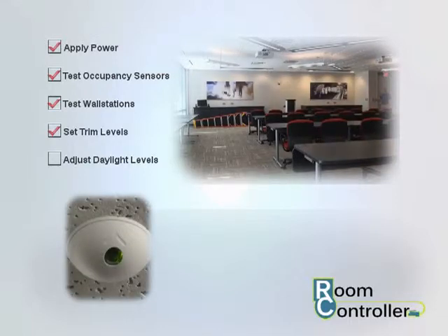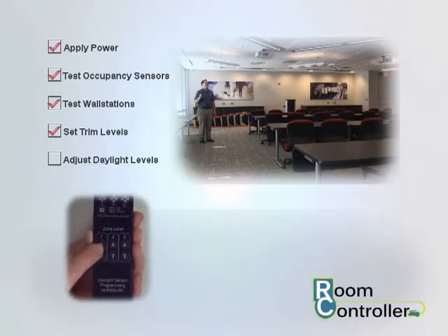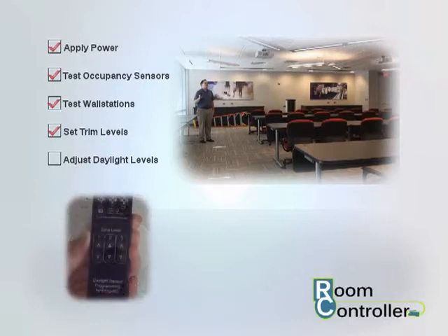After lighting has been turned on, look at the daylight sensor lens. If the lens has a green LED that's on steady, refer to your installation instructions for details on making advanced daylight level adjustments. If the LED is off, point the remote at the sensor lens and press the zone's raise or lower button until the lighting is adjusted to the desired level. The daylight sensor's green LED will start flashing rapidly. Repeat this process for each of the dimming zones that need adjustment.